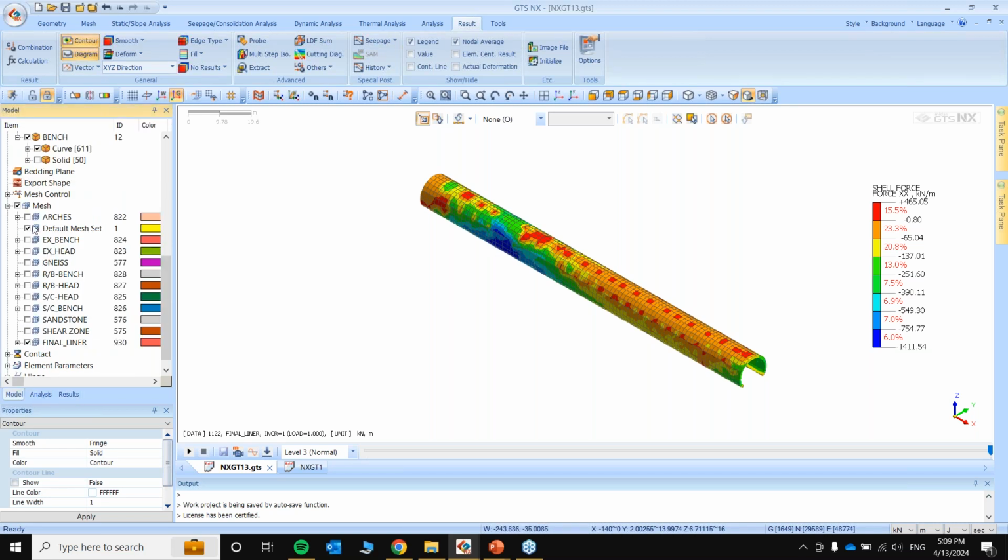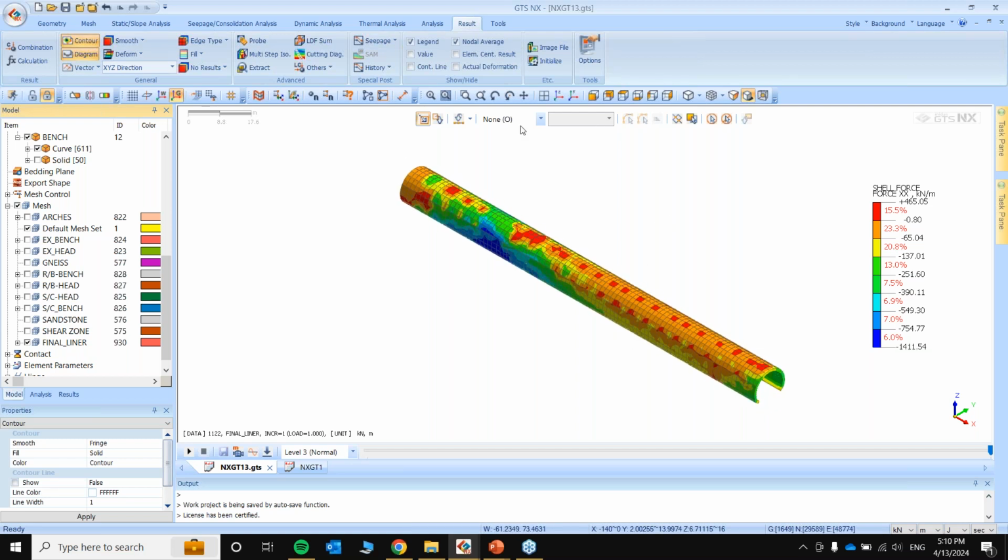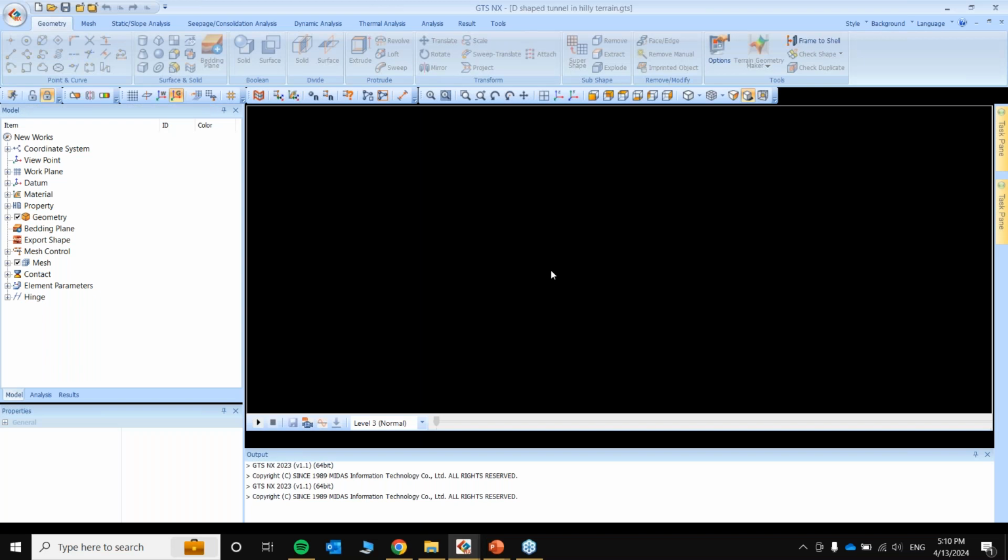With time, the principle of rock is that the rock starts to heal, as we say, or the stresses start to redistribute. But also with time, the primary support starts to deteriorate because of the creep, and the load is slowly transferred to the final support. I hope the models were clear to both of you in terms of interacting support and non-interacting support. Finally, I had one more thing to show you, that is the portal stability. For that, I had a third model.